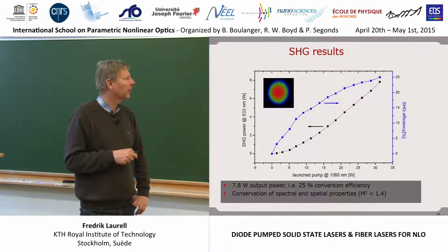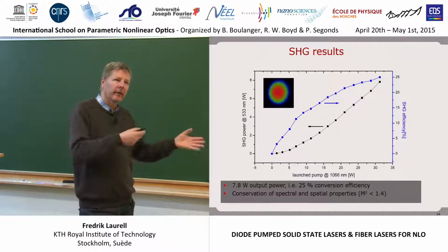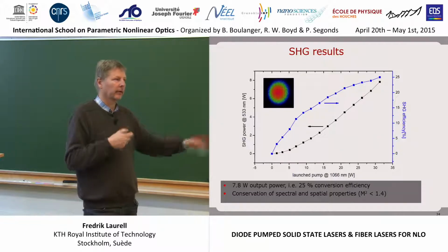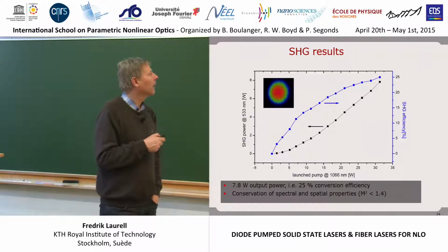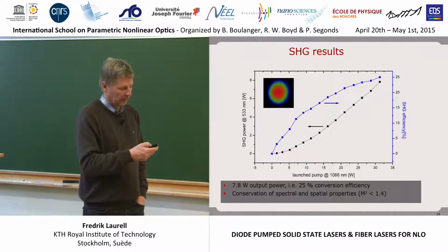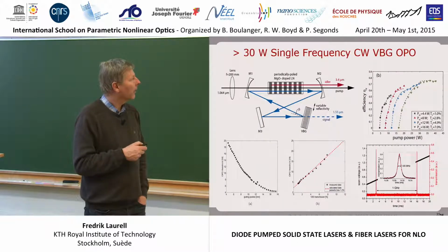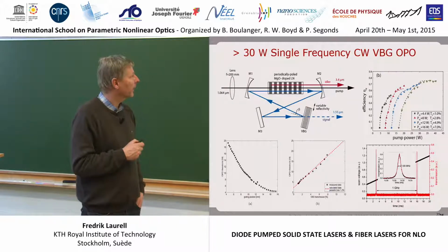KTP can go to almost 15 watts before we see the same features. But we had 100 watts to work with here, so we don't use our laser at all. Then we have been looking at ways of compensating for these thermal effects: changing the focus, cooling effects, chirped gratings, etc. This is a work in progress. A lot of thermal simulations have been done on this, and Peter is writing up his thesis together with Staffan Schönhammer, and they are working on this together.